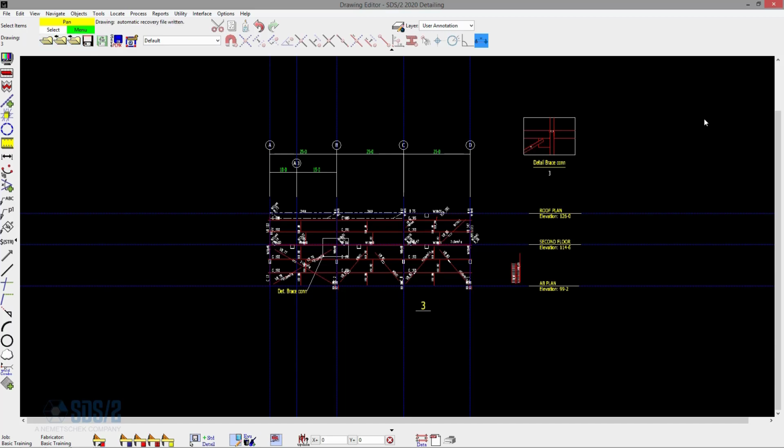I'll save that view. The next video, we'll go ahead and talk about creating our sheet outlines and loading our sheets for all of our erection view details, member details, and submaterial details, as well as looking at the piece mark changes for loading those members onto a sheet, and what options we have to update those piece marks to our sheet marks. We'll also talk about some other commands as far as search and replace, adding items to multiple sheets at a time, and some basic revision options for the revision charts and bill of materials.